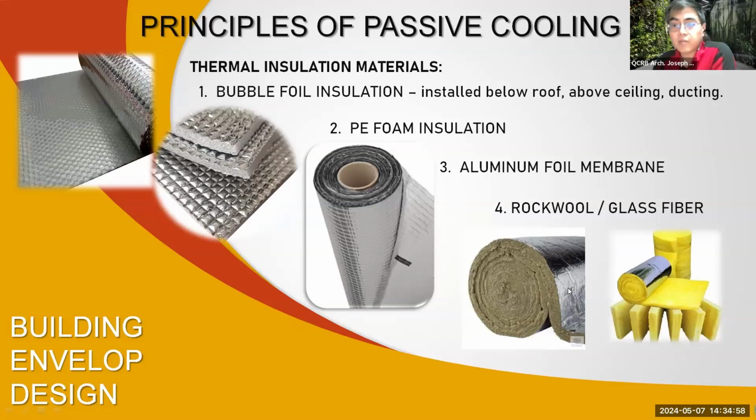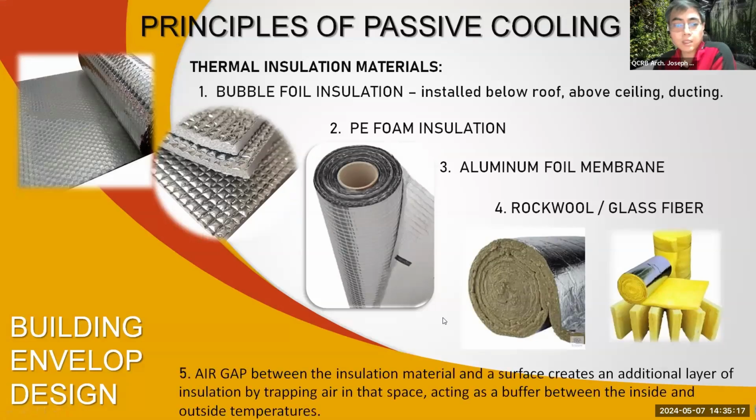Rock wool and glass fiber naman, no? Aside from insulating heat, it also insulates from noise, no? So kung maingay like if you live nearby an airport or yung highway, no? Ideally, you use a rock wool or glass fiber insulation over your roof or between your walls, no? See, the air gap between the insulation material and surface creates an additional layer of insulation by trapping the air in that space, acting as a buffer between the inside and outside temperatures, no?